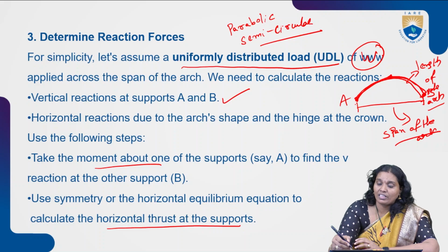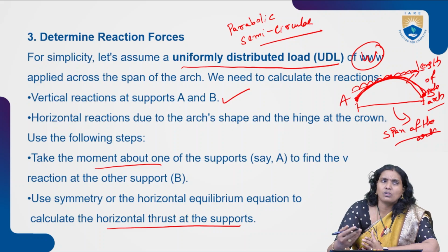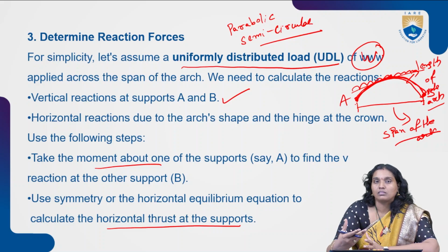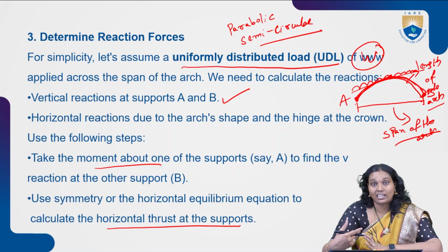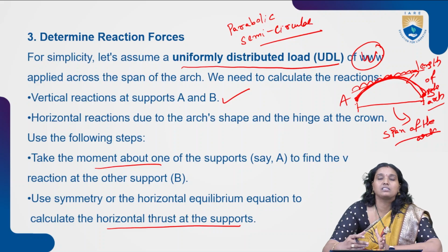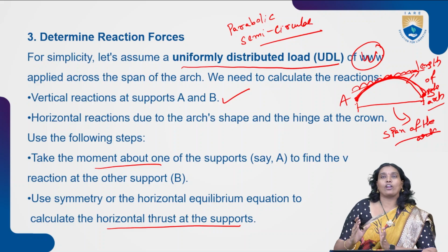Consider whether we are going to use a uniformly distributed load, a uniformly varying distributed load, or concentrated loads, so a mix of different loads may be considered. It depends upon the design and where we are going to apply it, and how it considers all these characteristics. These are the parameters in general, but to simplify things for understanding, we are considering here a uniformly distributed load across the span of the arch.